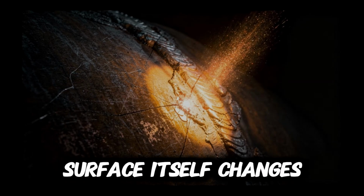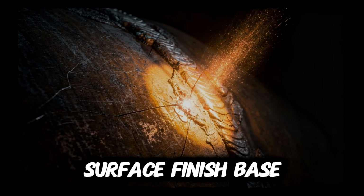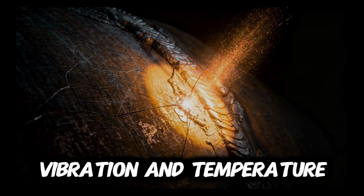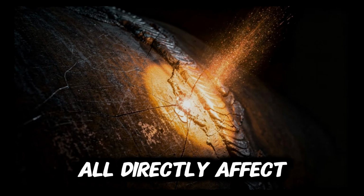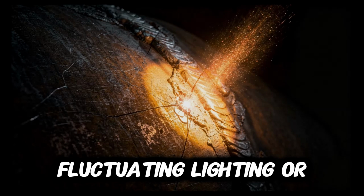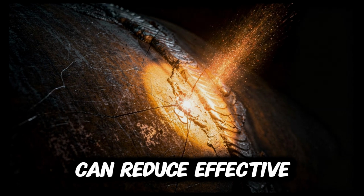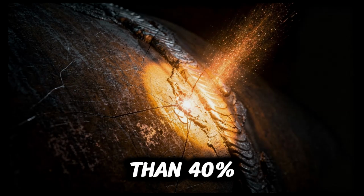And the surface itself changes how we see it. Absolutely. Surface finish, base color, humidity, dust, vibration, and temperature all directly affect reflectivity and detection capability. Fluctuating lighting or surfaces contaminated with oil or grease can reduce effective sensitivity by more than 40%.